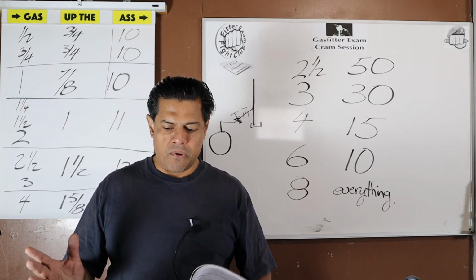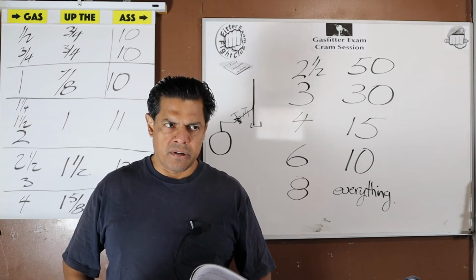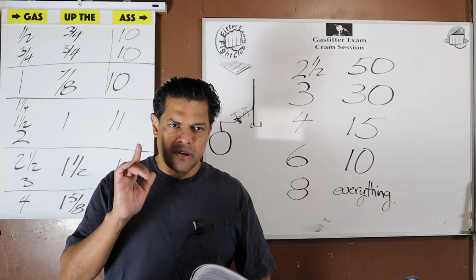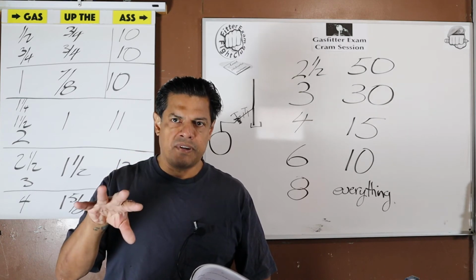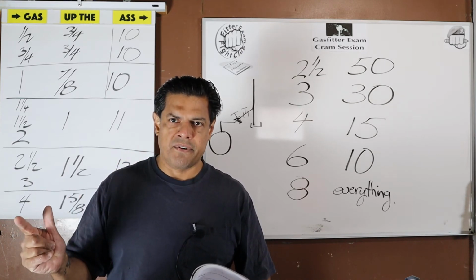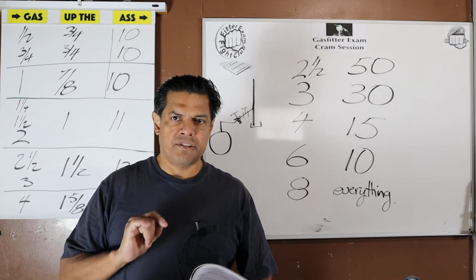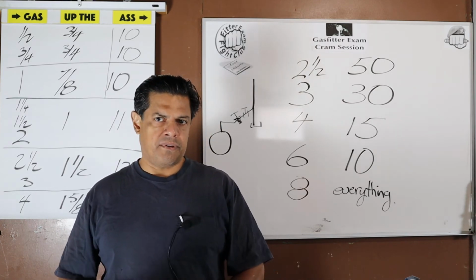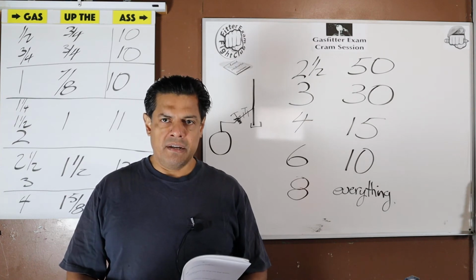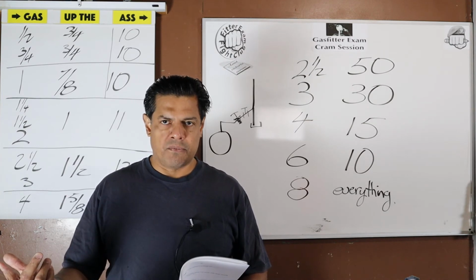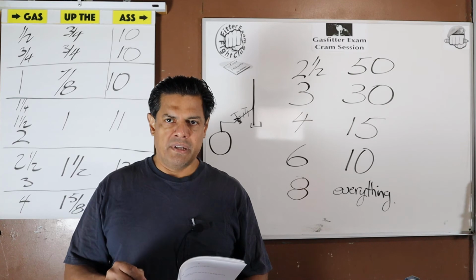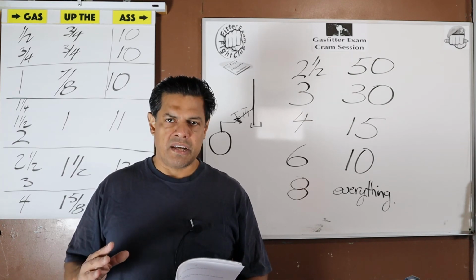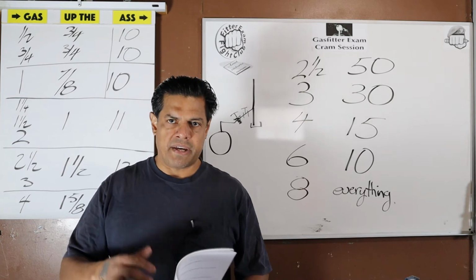For all the gas testing pressures, in test 3 we learned that if we're running piping in a corridor under the specific conditions that the code gives us, the test pressure for that piping alone is now 10 psi for 30. I put that in the beginning. That's just so much more information. But when did I give it to you? After you got the main gist of the table under your belt and could handle that, okay?